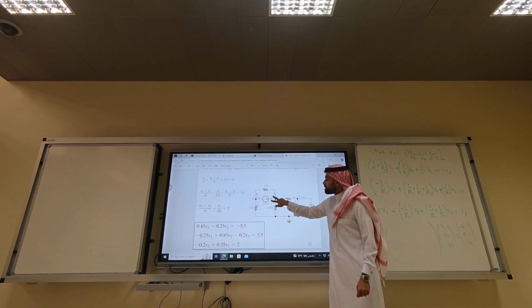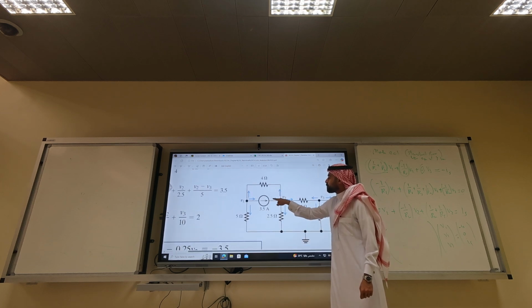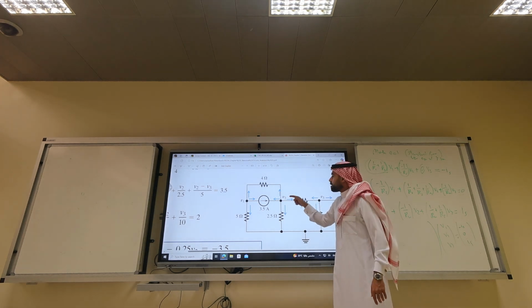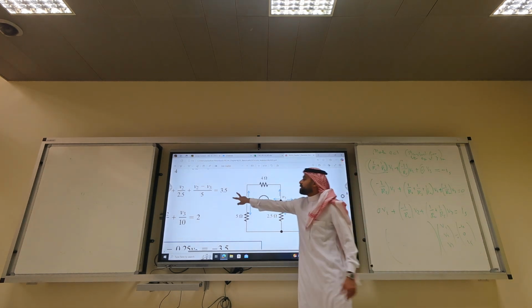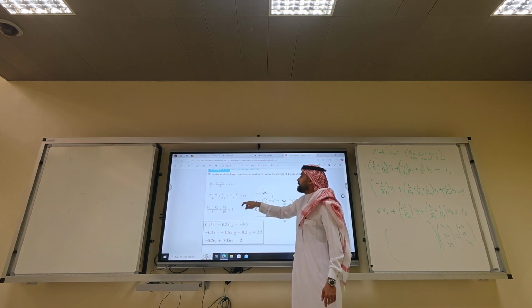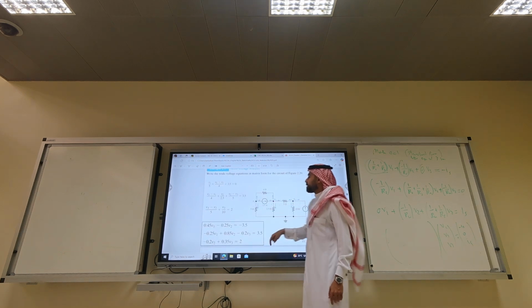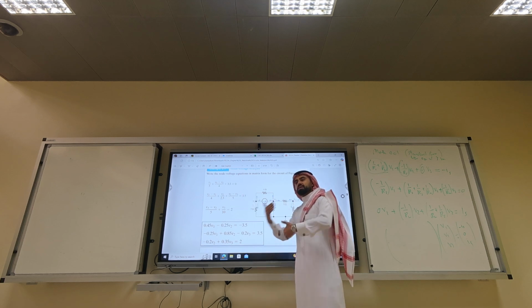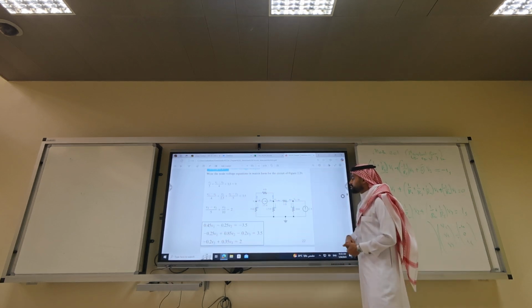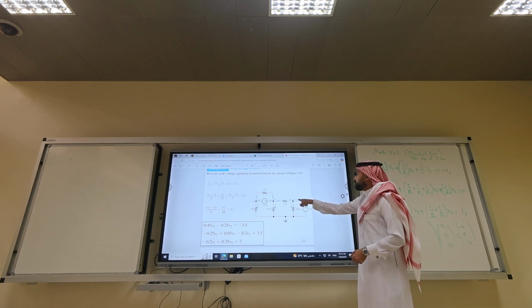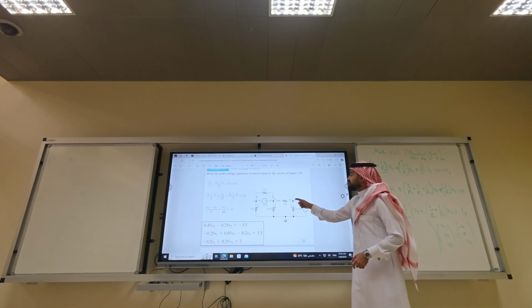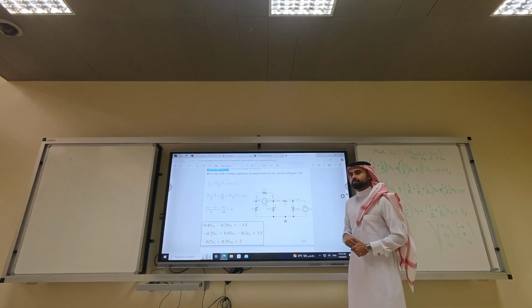The arrow current, the blue one, it's minus 3.5. So in the equation we said everything is out, minus 3.5 equals 0. He skipped a step here and he put equal 3.5. I like it to be minus 3.5 equals 0 and then you fix it later in the standard form. Last equation, what's the blue current? Minus 2, so he put a 2 here. V3 minus V2 over 5, V3 minus 0 over 10.